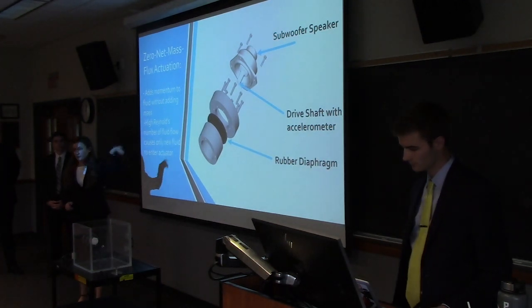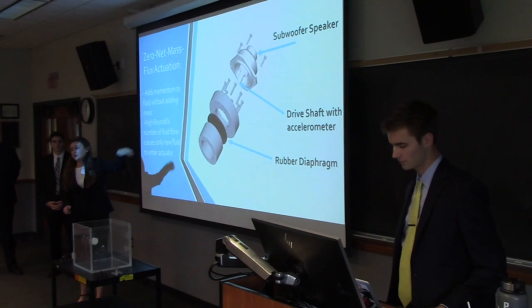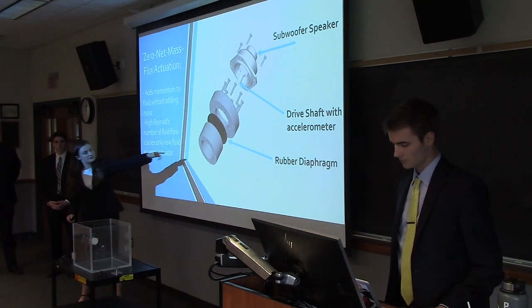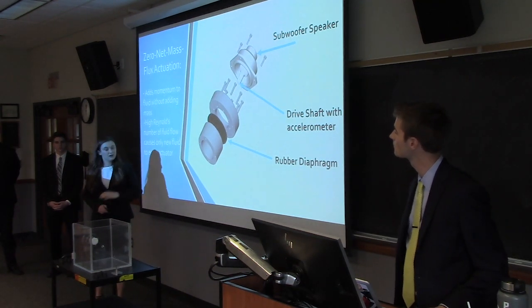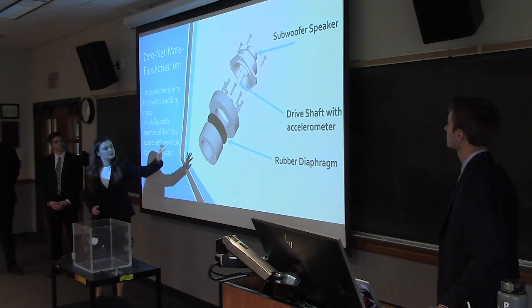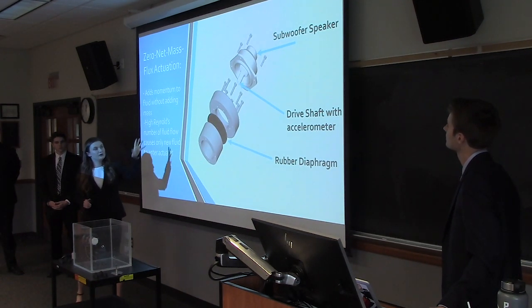This drive shaft is in turn attached to a screw that is threaded through this rubber diaphragm. So when the drive shaft moves from the speaker, this pushes the rubber diaphragm, and that pushes water through the tank through an orifice that is attached here. So there are little holes that push the water through and shoot out into the tank.